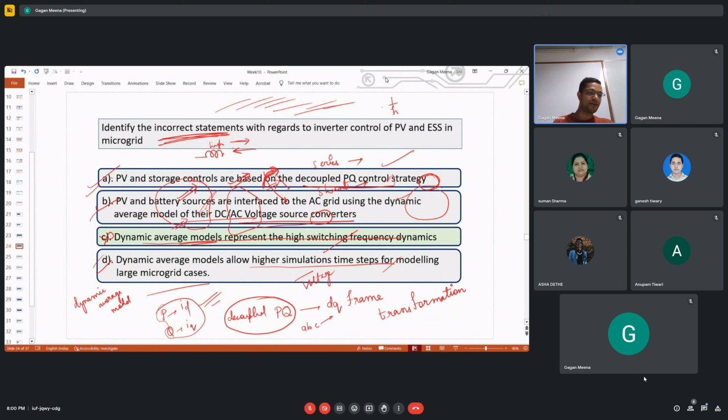Next question: the function of a diesel generator in the AC microgrid is? First is frequency regulation by changing mechanical input. Second is terminal voltage regulation by varying field current through excitation. And third, normally excited synchronous generator operated at 0.8 power factor. Option D, sir. Option D. Terminal voltage regulation by varying field current through excitation. Why not A? All of the above is the answer.